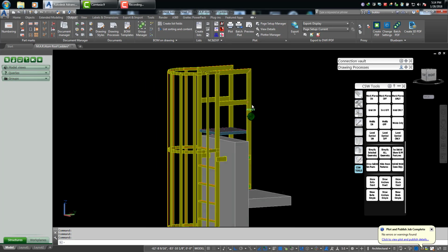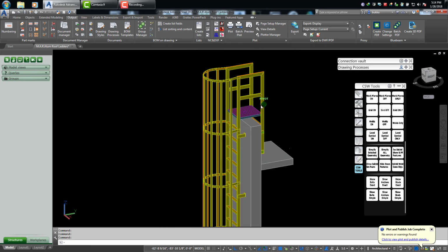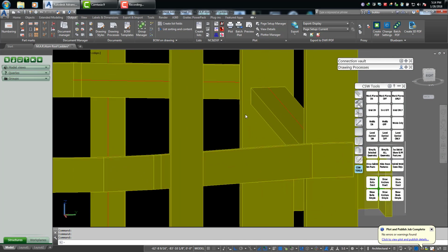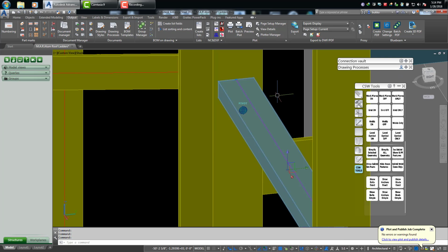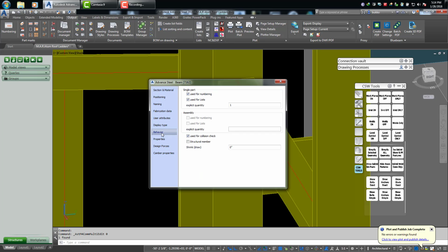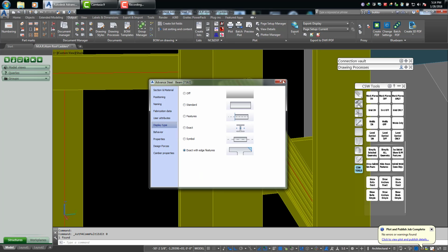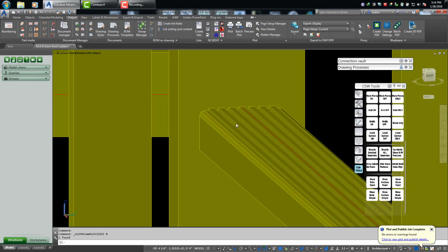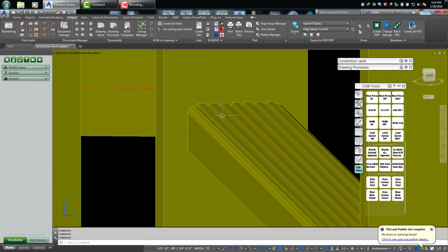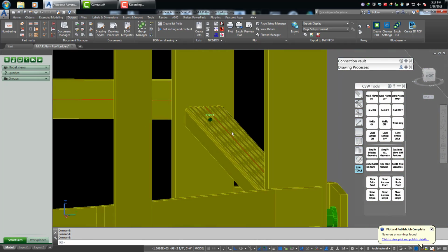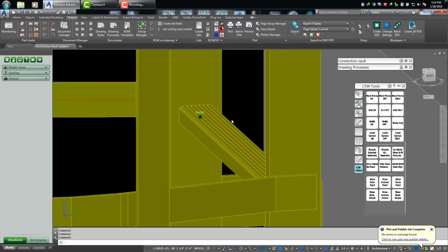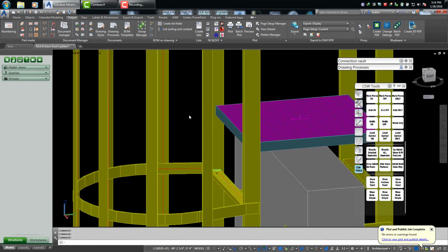Here's the ladder type that we build. This is an all aluminum ladder. It uses a 2x1 channel for the rungs, and that's an extruded channel. If you look at the actual exact configuration, it's got some step or non-skid raised surface here. This is a profile that I created and inserted into the ladder macro, and that is the aluminum rung that we use.